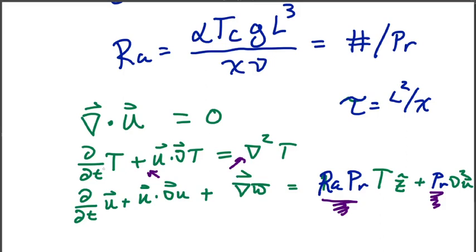This system has some rich dynamics. We'll be learning about those later on, but it's our first experience with a fully coupled system of equations with a non-trivial active scalar driving the momentum equation, and with the momentum equation then reacting back on that active scalar. If we had some boundary conditions here on t and on u, we'd be ready to go forward and get solutions for this. Depending on those choices, your system can either be unstable to convection or it can present internal gravity waves under the Boussinesq approximation.